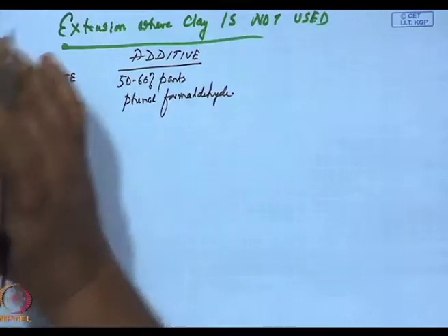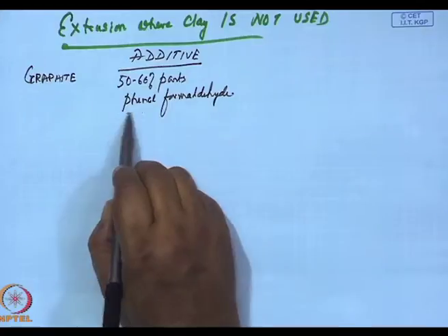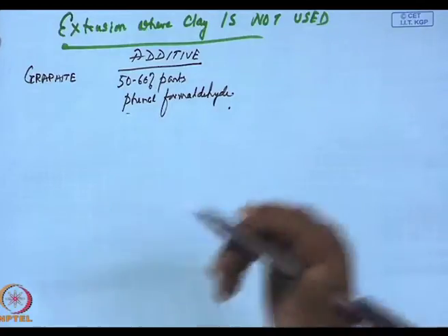because when I have extruded it, I can burn this phenol formaldehyde off, which will leave a lot more carbon, and this carbon will be really in the submicron range. I would rather say in the 5 to 10 nanometer range, which would aid in sintering of the graphite grains which I have started with. Normally, in extrusion, the finer the grains, the better the extrusion. And normally we use 1 micron sized or less powder of the basic matrix.